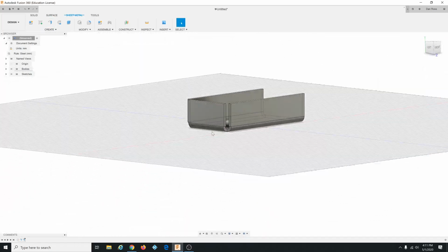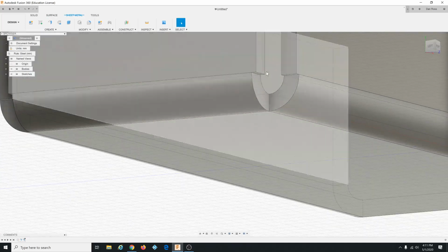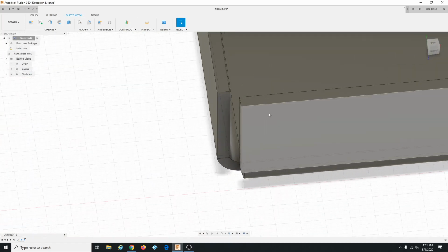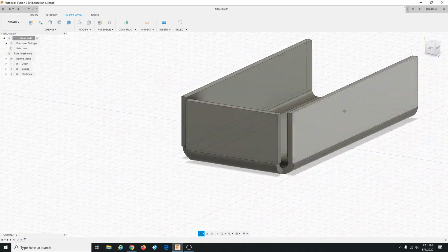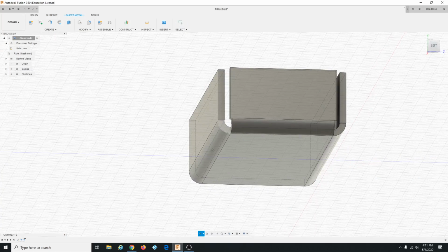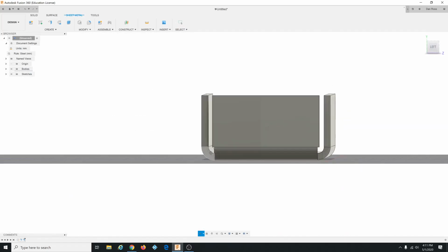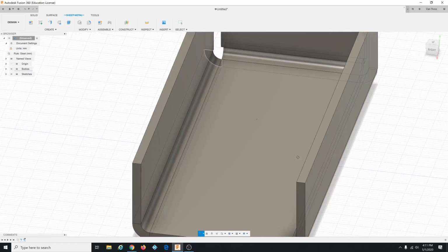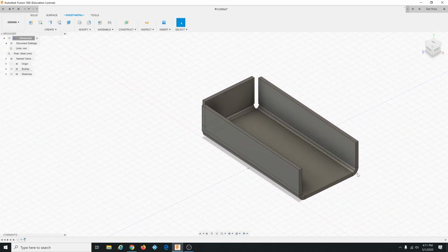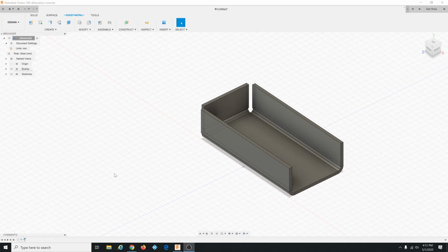So now we have this thing, and it does this edge treatment here, right? There's a certain thickness to the material, and there's a certain way that it's doing these corners here, and that's in the rule. All of those things, bend radiuses and stuff, like different materials can bend at different radiuses. They might crack. You know, like aluminum is notorious for cracking if you bend it too sharply. So anyway, there's lots of features like bend radius and material thickness and other features that are in the rule. All right, we can make a new rule.